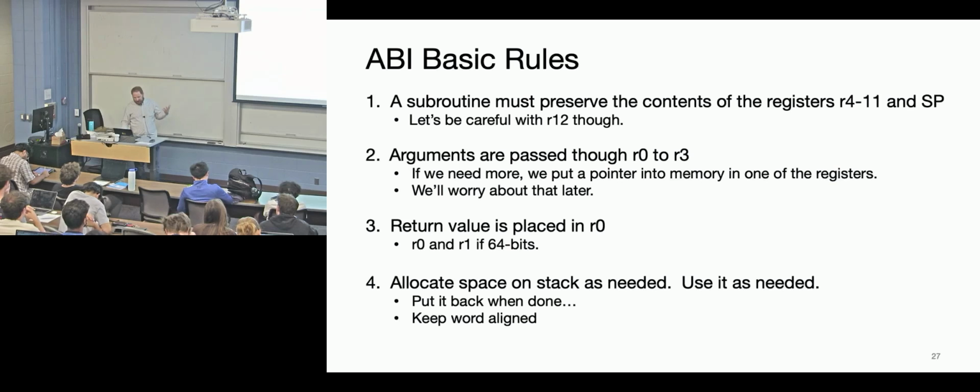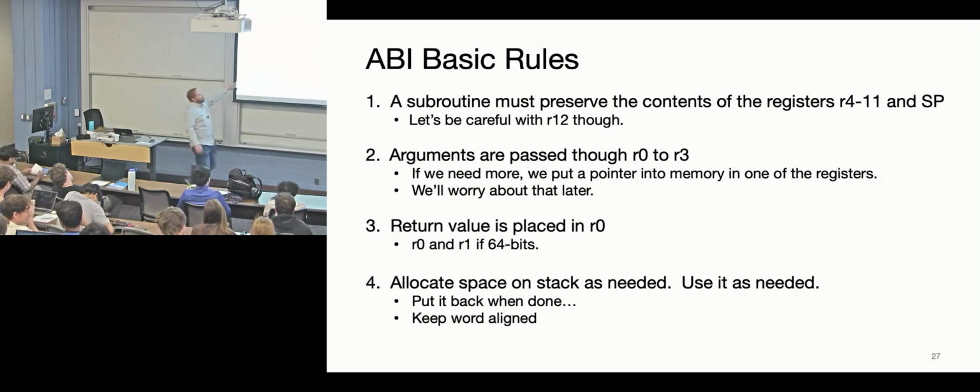So you're going to pass your arguments through R0 to R3. You start with the lowest one: R0 is the first operand, and then R1, R2, R3. You could pass a 128-bit value that way if you wanted to. Your function just has to know that's how it's going to be taken. And then you can pass return values through R0. Typically, it's only R0 through R1, although I guess there's no inherent reason why you couldn't do the other ones. The convention is all returns go through R0 and R1, starting with R0 for your first return.